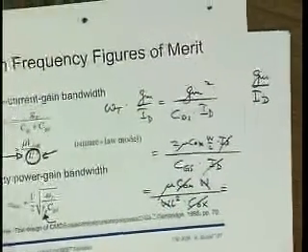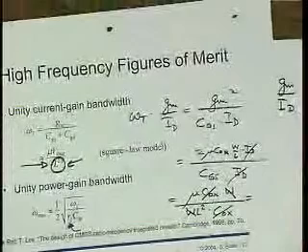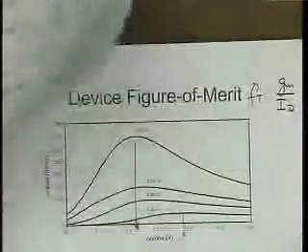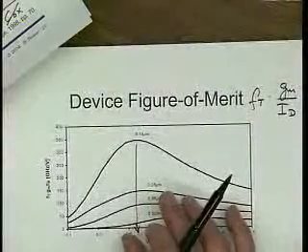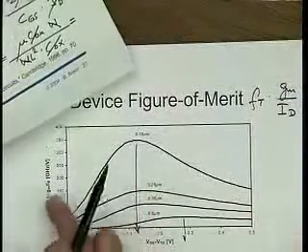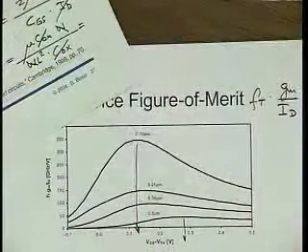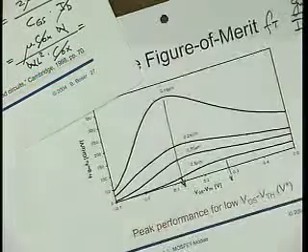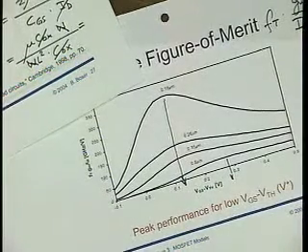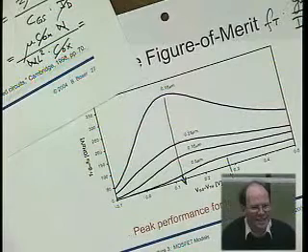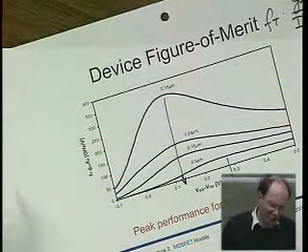So I guess what I could have done is multiplied this figure of merit with L squared, and then said, well, this is the value of the mobility as a function of VGS. We would have looked at this and said, well, what good is this for? But you're right, they are connected like that.